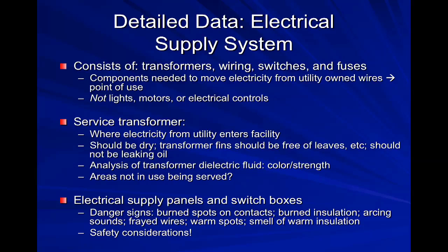Whether the equipment hooked up to it is working or not, it might be shut off, but if the transformer is still running, it still has power going to it, even though the equipment connected to it isn't turned on, there's still energy being used there and quite often lost. So be really careful when you're looking at these, especially in the older equipment that perhaps you don't know as much about.